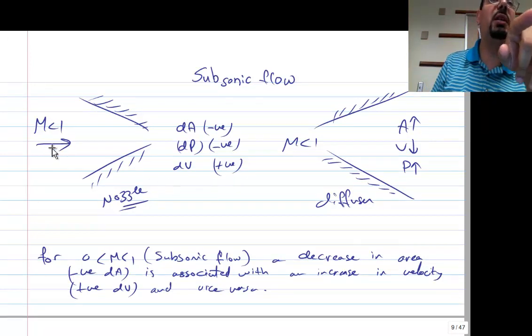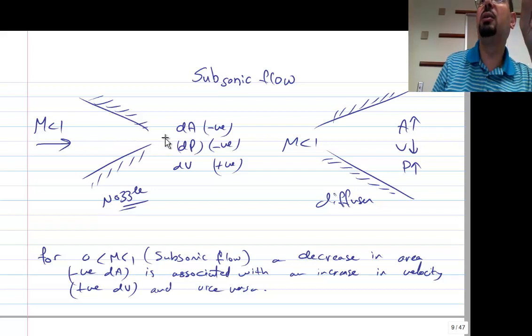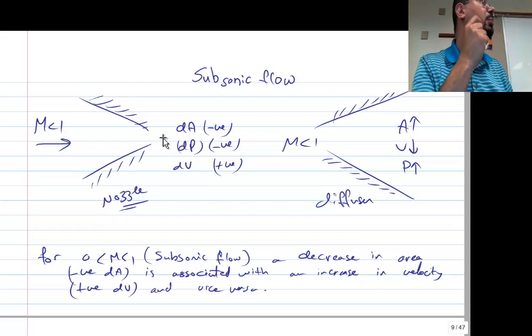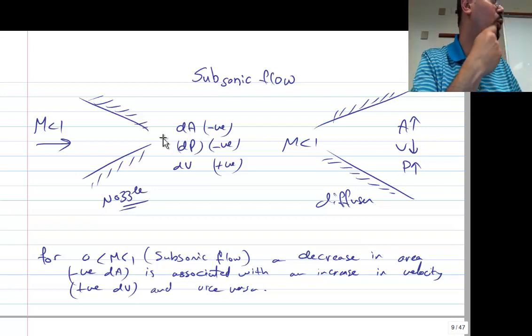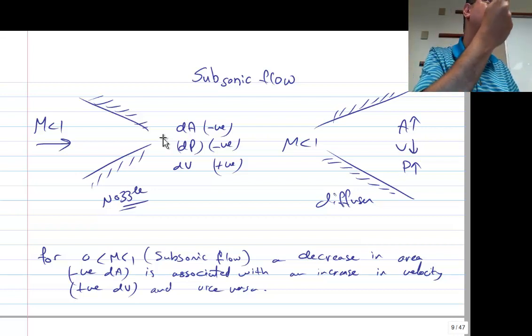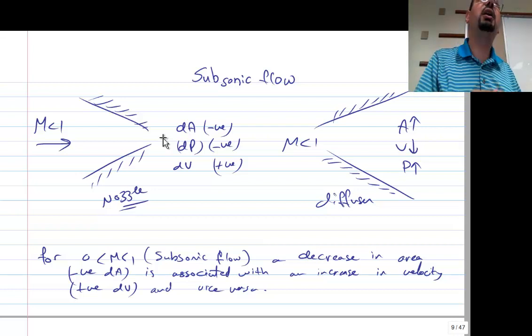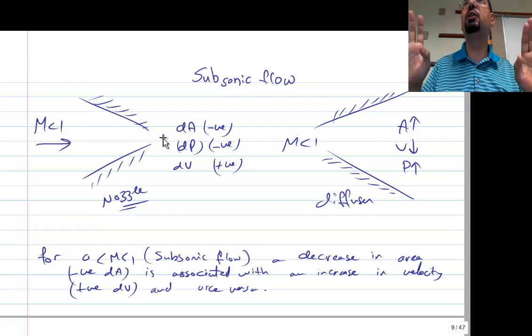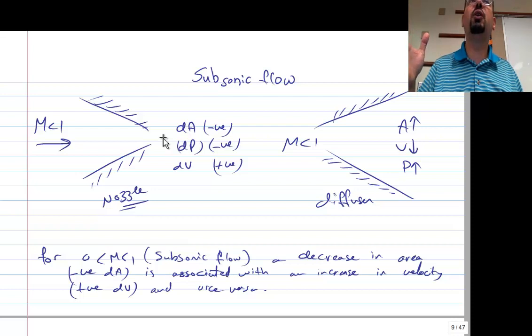From Fluids 1, we basically know this: you give me smaller area and I will speed up, or give me more area and I will slow down. I speed up because I want to keep my m dot the same, because my density didn't change that much. Keeping m dot the same is the conservation of mass. There is nothing called conservation of volume, really.